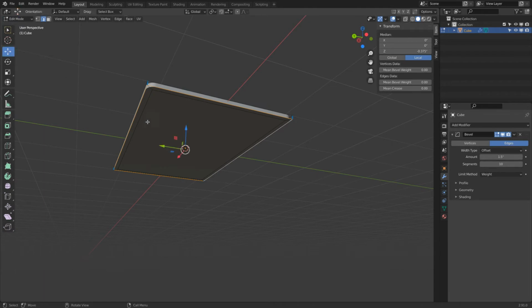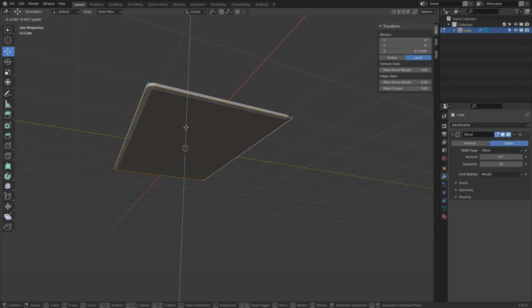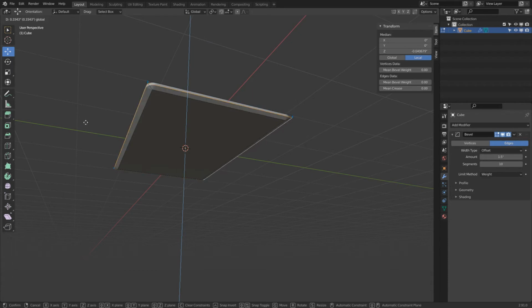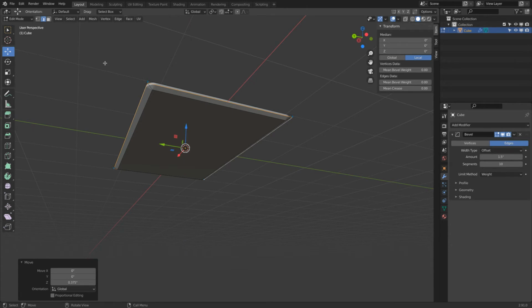We go to move command. Now there are two ways how I can do this. I drag this one up, upper left corner here where my mouse is. There you see the value, and I can now type in point or period 375. Be careful about the direction. So as you can see, I'm flipping the direction by hitting the minus key. And then I release the left mouse button, and there we are. Or I just do an undo.